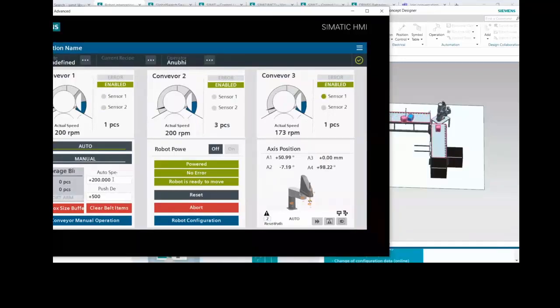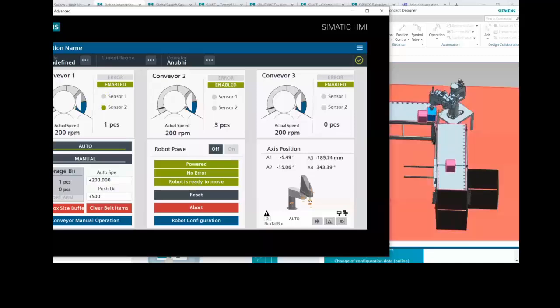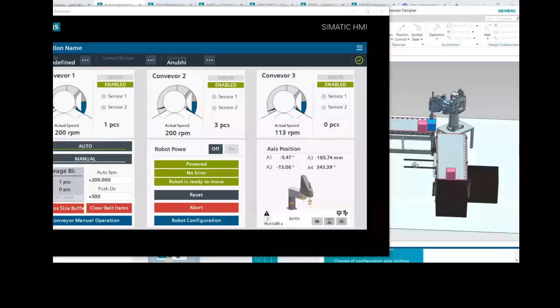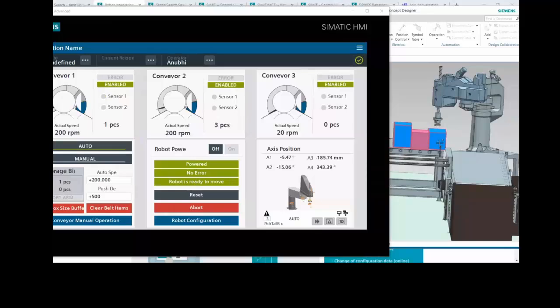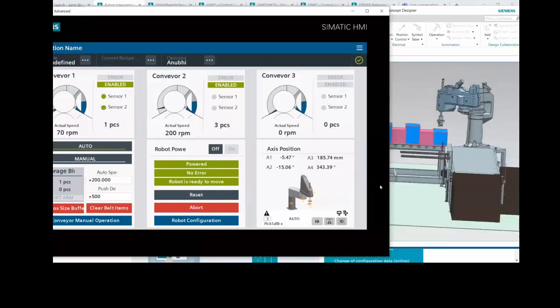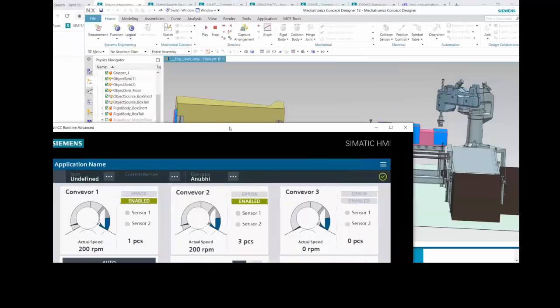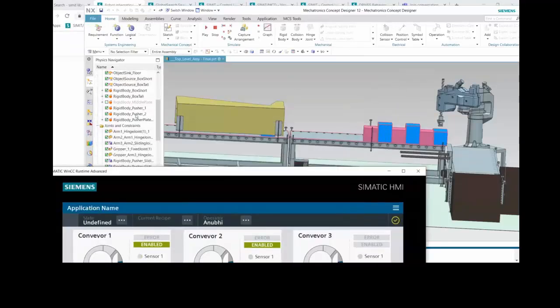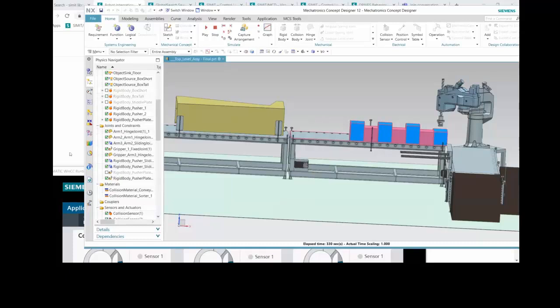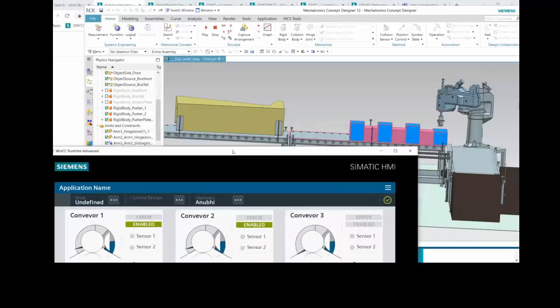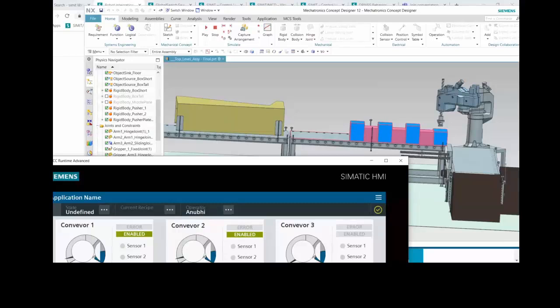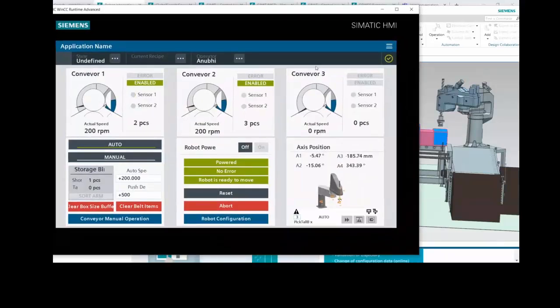Now my robot does the pick and place, and it threw that around because I didn't put it in the auto mode earlier. And you can see now it was expecting to see a tall box there, but it's not the tall box. So now it's all confused, and it's now saved there. So we can then integrate these errors can then be fixed in your code, and you can introduce some sort of checks that make sure that your conveyor doesn't move if something is already there, if something is off the conveyor. And we can then go about going auto or manual and moving the conveyors back and forth.